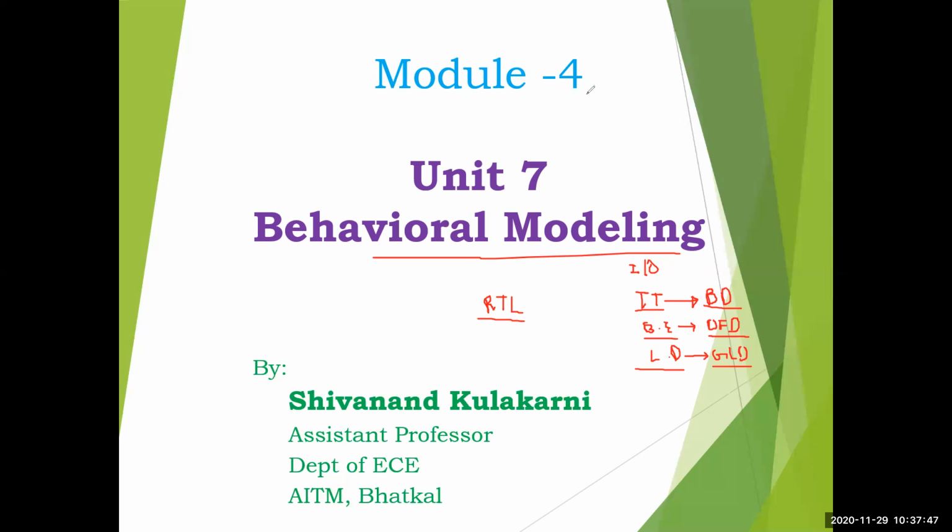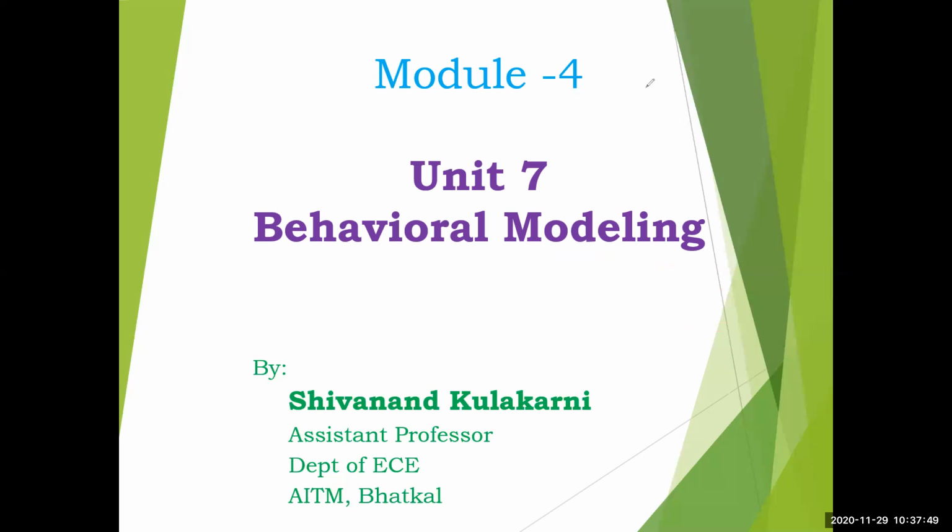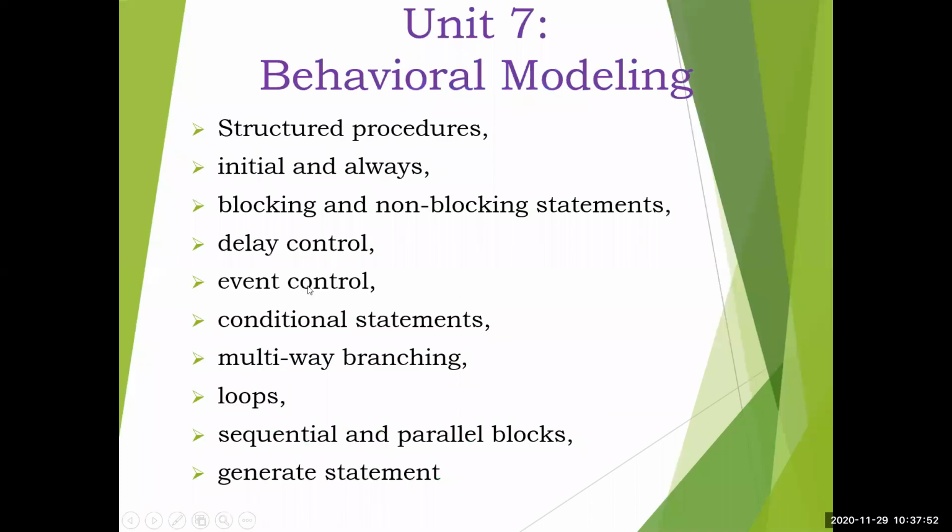Now let's look at what we are going to see here. These are the topics we have in behavioral modeling. First, structured procedures: initial and always. Initial you have gone through already in some of the stimulus blocks. Along with that, now we'll learn another keyword. These are the two blocks which will be present in all behavioral modeling. Then we'll learn about blocking and non-blocking statements, then the delay aspect of behavioral modeling.